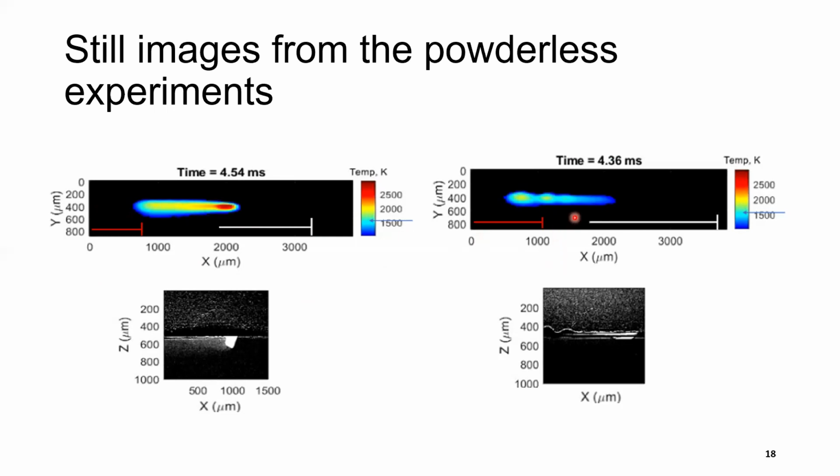However, in the next track, you do see that the temperatures in between these balled up regions are slowly cooling down while the surfaces of these balled up regions are still very much liquid, suggesting that solidification is occurring in between those balled up regions.